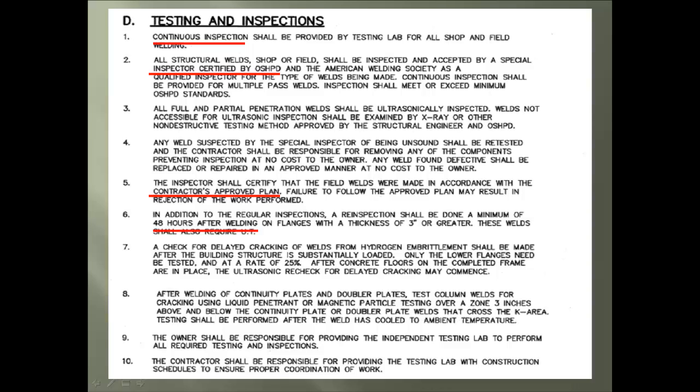Notice the 48-hour rechecks of welds on flanges 3 inches and thicker. Here, an alert for all personnel. It's a check for delayed cracking after the structure has been loaded with concrete. The owner will provide the third-party independent testing lab. And it's the contractor's responsibility to provide the testing lab a schedule for proper work coordination.